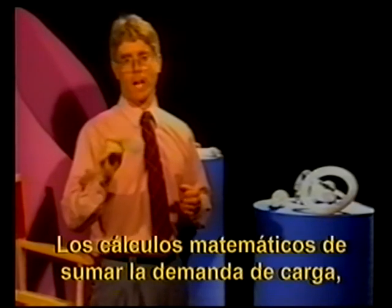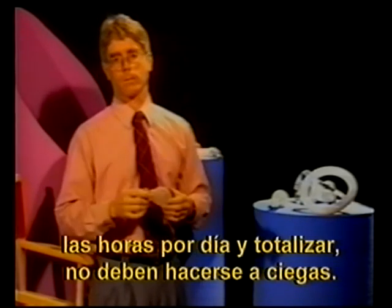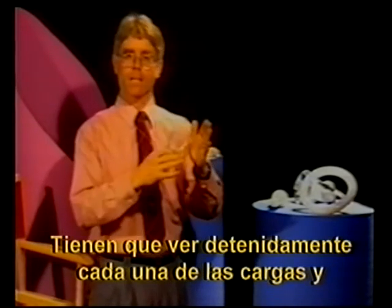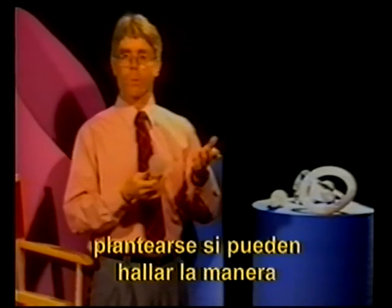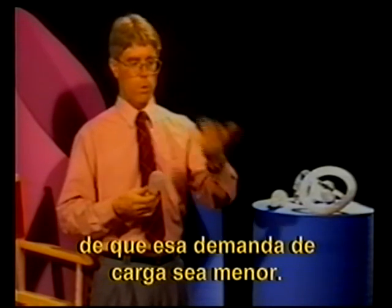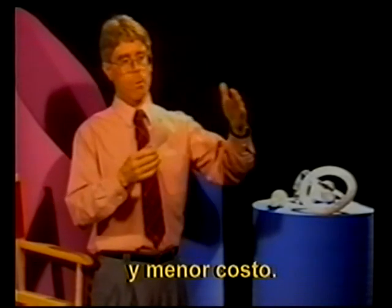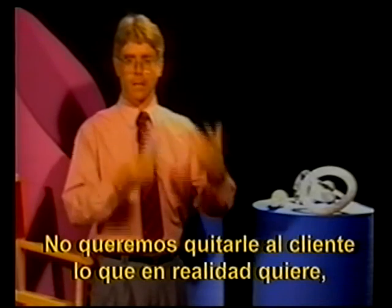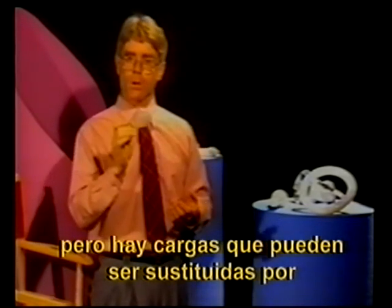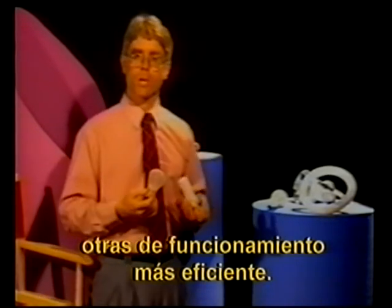In doing the mathematical calculations, adding up your load demand and the hours per day, you shouldn't just blindly do that calculation. You should look carefully at each one of the loads and ask, is there any way that I can make this load demand less? That's going to require fewer modules, fewer batteries, and lower cost. You don't want to take away from the customer what they actually want, like lighting or refrigeration or appliance use. But there are a lot of loads that can be substituted that would give you much more efficient operation.